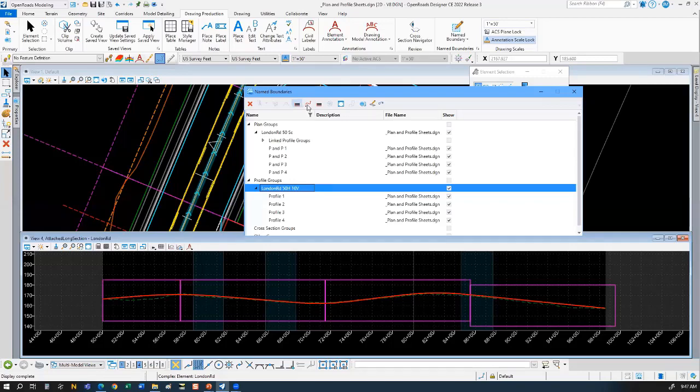Now, before we get there, there's this one intermediate tool or a dialog box that we're always going to want to see. And it only will show up if you turn on this button here called the Show Create Drawing dialog. When you turn this on, it will actually show you that intermediate step. Now, even if it's just a matter of just reviewing it and clicking OK, that's great. But if you need to make changes on it, the only way you're going to make changes on it is if this button is turned on.